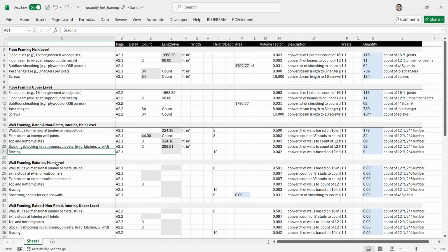So for every 10 feet of your walls, you put 1 diagonal bracing. Okay, so let's assume that's the standard. But it can be as many as 1 for every 10, or as few as 1 for every 20 feet of linear distance. So what we really need here is the total length of your walls.